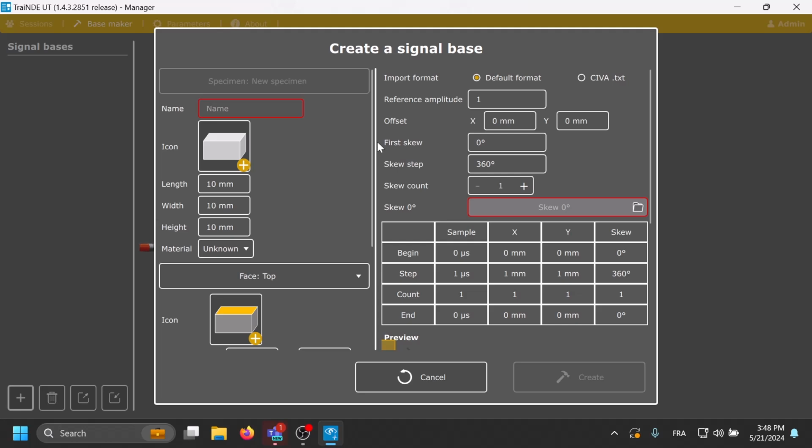Also, in the exercises we are providing, there are many kinds of defects. There are delaminations, porosities, cracks, lack of sidewall fusion. There already are a lot, but if you need another one, it can be added.